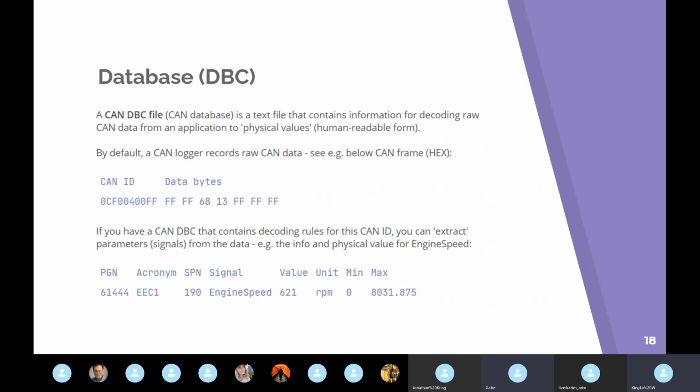Yeah, it's cool because if we just put all our signals onto CAN, then if you plug your one CAN dongle from the CAN bus in the car to the PC, it can automatically convert all of those messages into curves. If I stomp on the foot pedal, I can see the foot pedal curve going up on my computer and all that stuff. So it's going to be sick for seeing that data. Yeah, very good to visualize data.